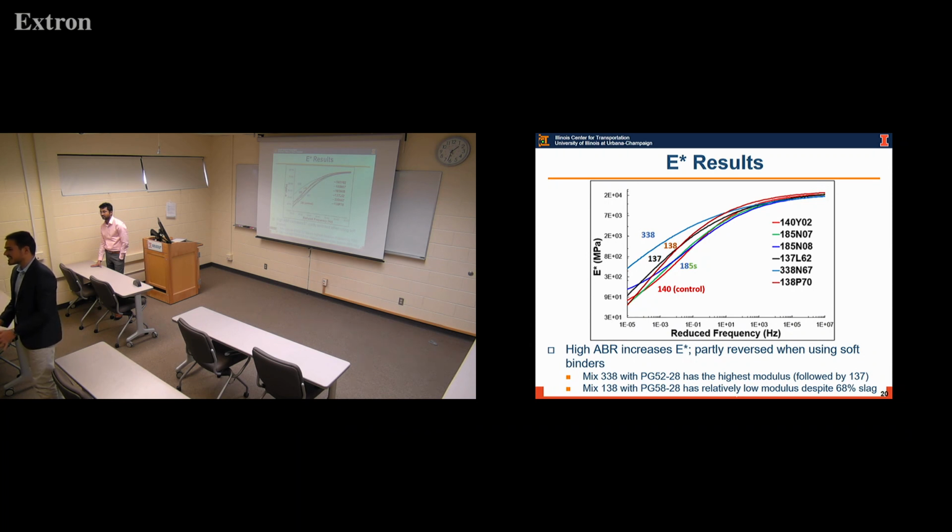Here we're just looking at the size, but the strain magnitude differs between a smaller and a larger fracture process zone. That was limited here, and I would be careful when we assume that the area is directly related to the energy. It's not only the area, it's how much strain we have there. This is another thing that was not included in the study.